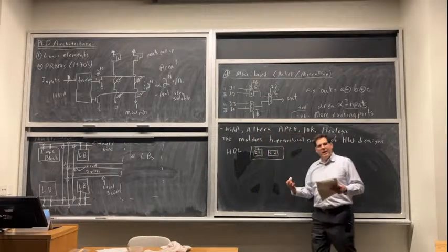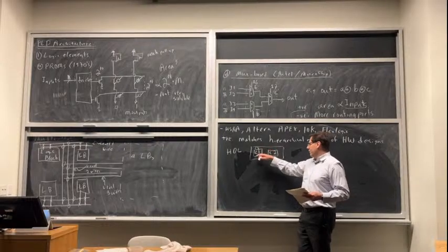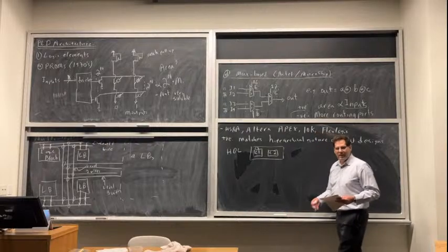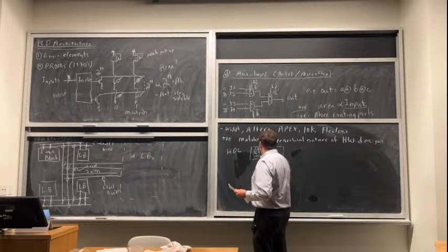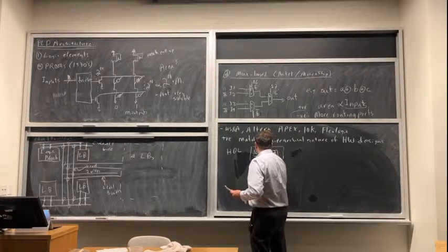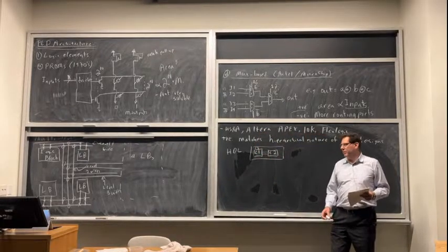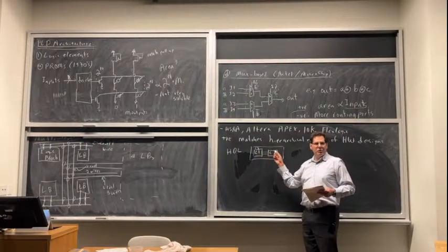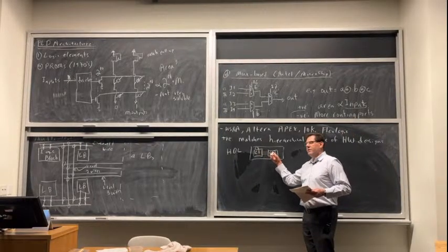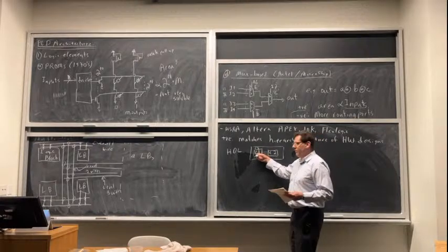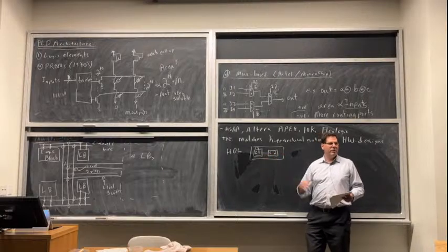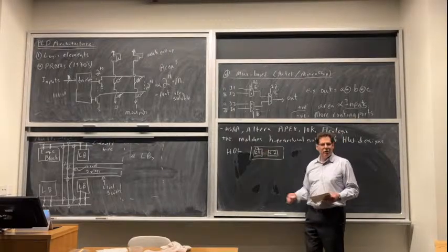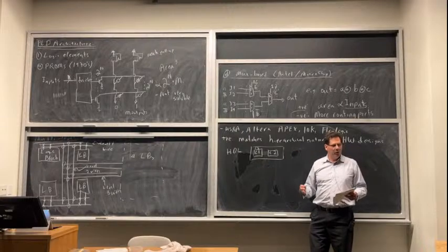Okay, so that's how HDL works. A module C3 instantiates this submodule and this submodule. If I go inside these, they might have submodules and so on. It's fundamentally hierarchical. And what happens is normally you'll have some connectivity between these. These will be hooked up with some signals, but the number of signals going between them is usually less than the number of signals that are inside of them. Some of the signals inside here will just be local, and they don't make it to the ports. And that's true at every level of hierarchy of your design. Some of the signals don't make it up to the next level of hierarchy. They're not important enough. They were local communication.